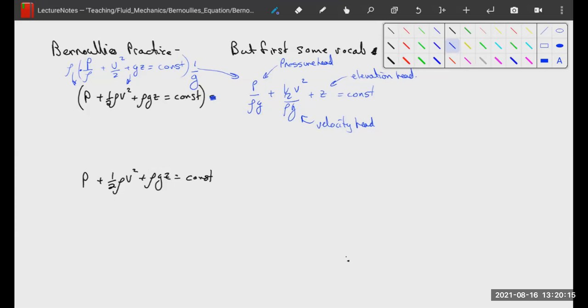When you measure the pressure, you see that the pressure head is 15 centimeters, so that you know the elevation head and the velocity head are X, and you can just subtract these things without multiplying by density and dividing by gravity, if you just keep everything in terms of height.